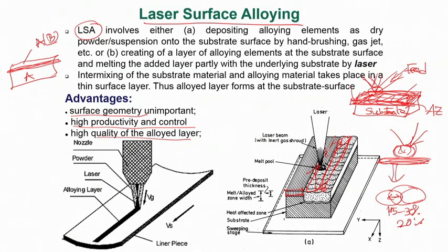So 20% of the width is undergoing remelting and realloying, and this is needed so that compositionally what we create at the end will be rather uniform and will not have a very sharp interface like this. Instead of making a sharp interface, we create a uniform layer, uniform composition throughout by way of this kind of overlap.